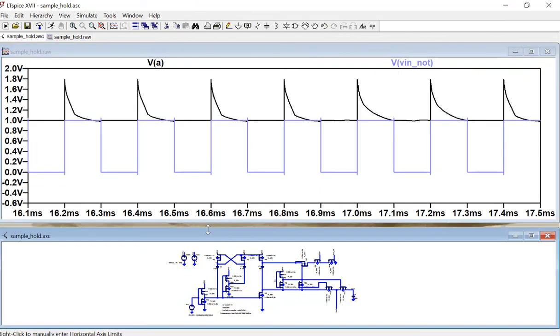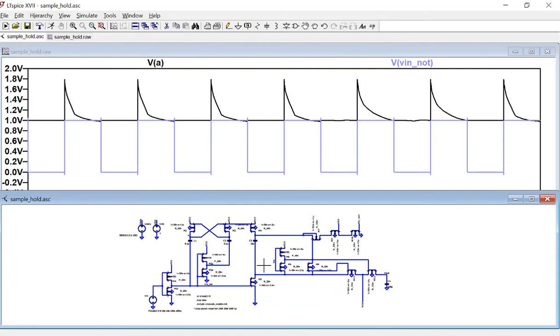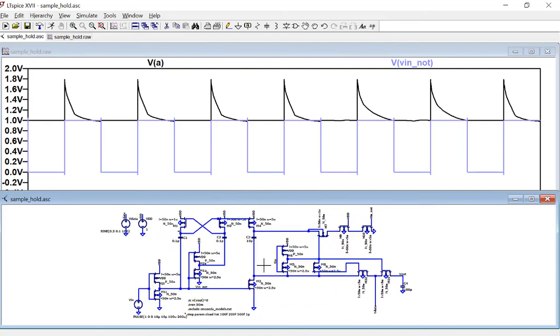All right. Like what I just analyzed. Whenever this pin is high, what is this circuit doing? It's pulling this to the ground, right? And it's turning this on and allowing VDD to pass to this point. So I'm charging up C3 to VDD, right? That's that cycle, during that cycle.